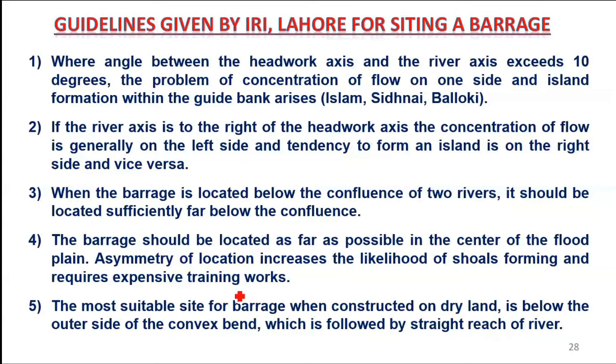Now, the guideline given by IRI Lahore for siting a barrage. They have carried out research. IRI means Irrigation Research Institute of the Punjab Irrigation Department. So these are the findings of the IRI. They say that problems arise where the angle between the headwork axis and the river axis exceeds 10 degrees.